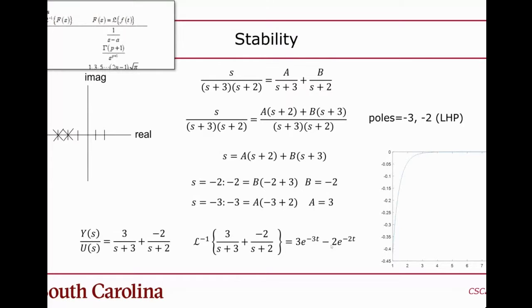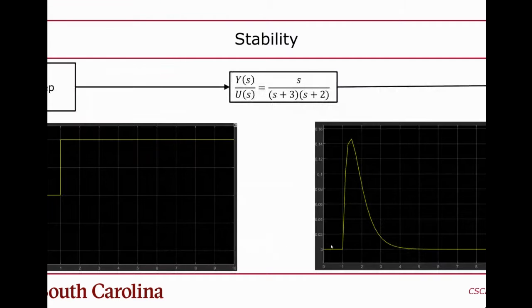So this would be the impulse response. Now, if I were to simulate this in MATLAB and give it an impulse, then I'll get the same plot. The difference is that by doing the inverse Laplace transform and then plotting it versus time myself, I effectively simulated this thing. I did this little simulation. I don't actually know how to simulate the step function or a sinusoid. MATLAB does that automatically, but I can do the simulation by hand for the impulse. And that's what I did.